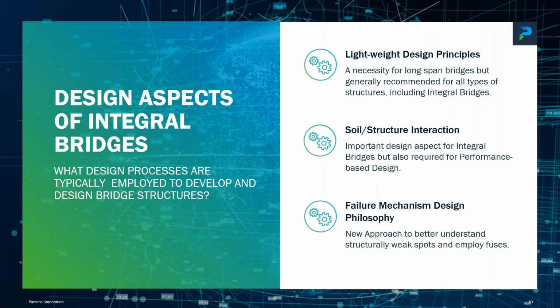Soil-structure interaction, I mentioned this already, is an important aspect of integral bridge design simply because the soil matters. If you have stiff soils, you have larger restraining effects. If you have soft soils, you have larger deformations, and you need to understand what matters and what you can tolerate. For that reason, I recommend the lower and upper bound soil spring approach, where you study how your bridge behaves under those soil conditions, and then you tune your bridge with the slenderness, with the stiffness of its members, so that it has the right performance that you would like to see.